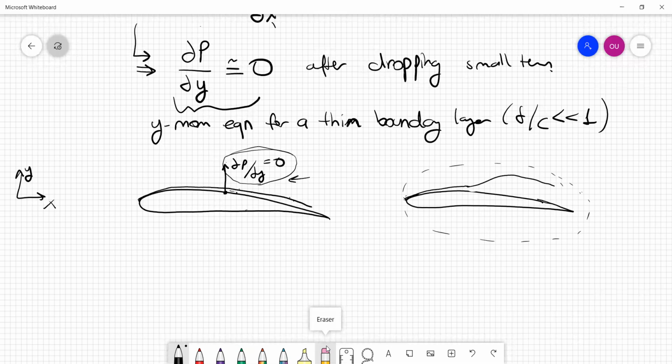You get your panel method CP distribution, and because of this transition process, and because of the fact that the boundary layer is a bit thicker but still attached, the CP distribution gets modified a little bit. Okay, so therefore, the boundary layer theory also tells us that it's actually useful to know or apply the inviscid flow theory, like panel methods, in aerodynamic analysis.